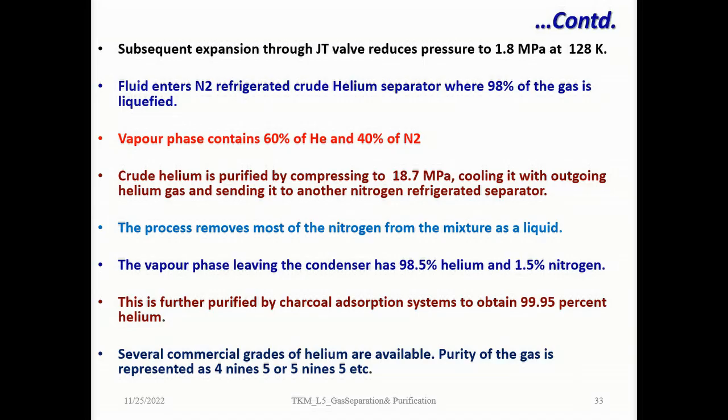This helium is now purified by charcoal adsorption to obtain 99.95% helium. And if you want to purify further, you use similar processes again and again, wherein it is adsorbed, and you get higher grades of helium. Several commercial grades are available.